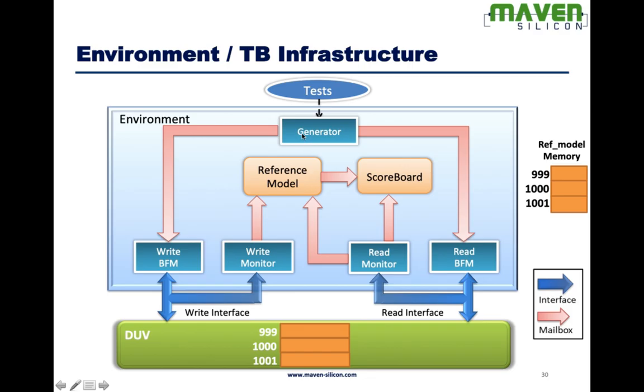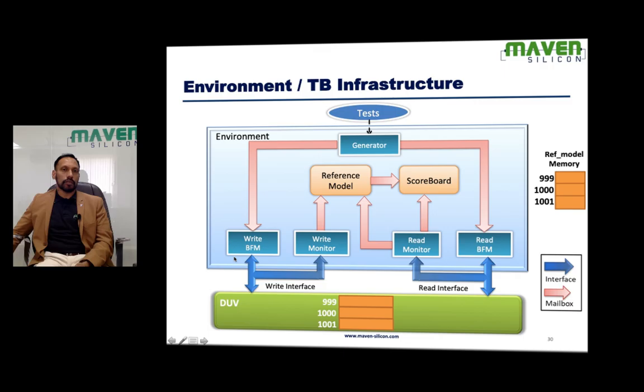Transactors are nothing but test bench components. So we use mailbox to connect generator with driver, and monitor with reference model, and reference model with scoreboard, or monitor with scoreboard. How you want to implement the data flow, based on that we can make the connections, and the connections will happen through mailbox. When it comes to connecting any test bench component with DUV, we have to use interface.